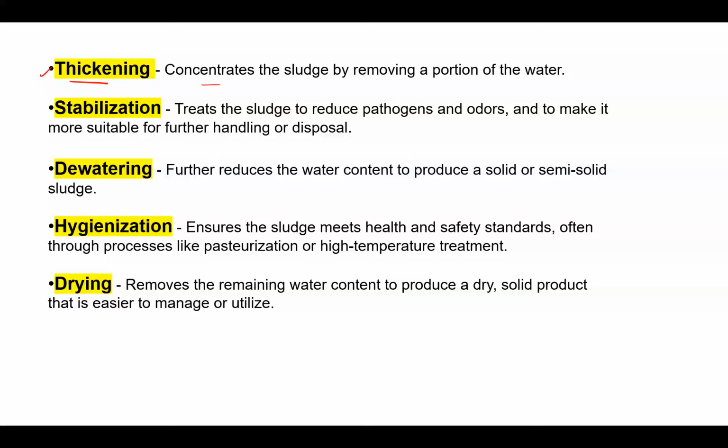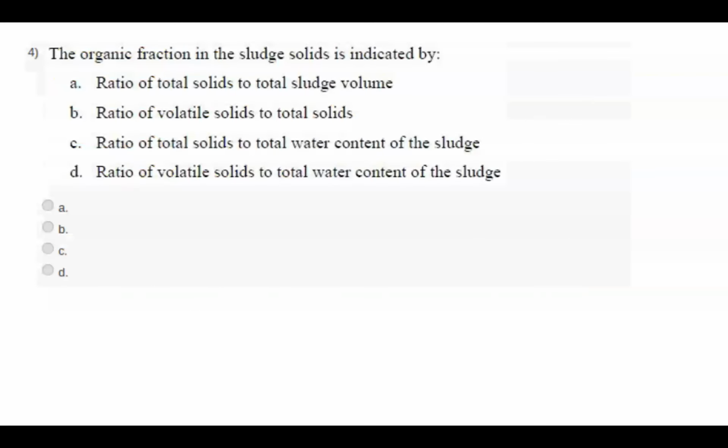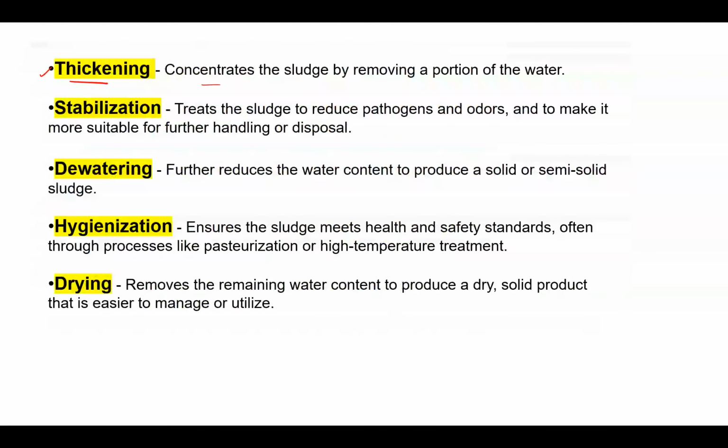Okay, so stabilization. What does stabilization mean here? It treats the sludge to reduce the pathogens and odors and make it more suitable for handling and disposal.